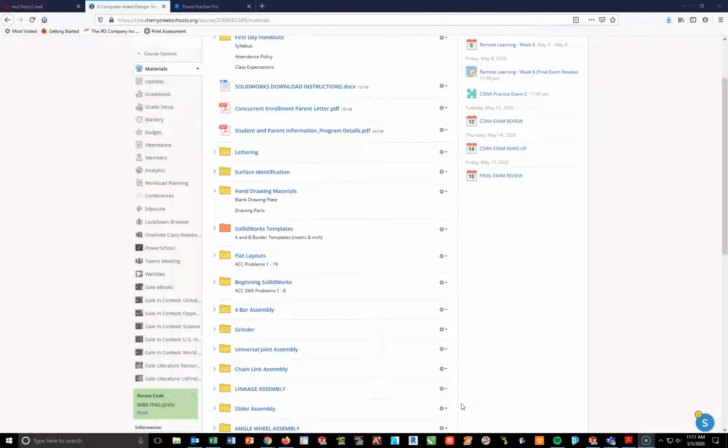What it's asking for is, it's telling me the unit system is going to be in inches, so IPS, inch pound second. It's going to be decimals up to 2 places. I'm not worried about where the origin is. Arbitrary means it can start from anywhere. But I am going to set up an A and a B on this so I understand the equation part. And the material will ultimately be alloy steel. What is the overall mass of the part in pounds?